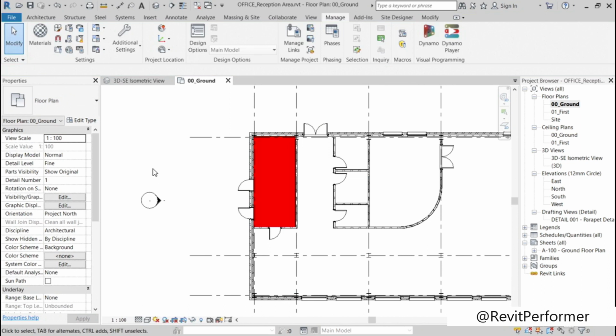Now that's fantastic for highlighting areas in your floor plans in Revit, but you might also have a similar system running in your AutoCAD drawings. So again, you can look at your AutoCAD drawings, decide on what is there, and then apply that to your Revit projects as well. But that's how quick and easy it is to edit fill patterns and edit those filled regions that you utilize those fill patterns as well.